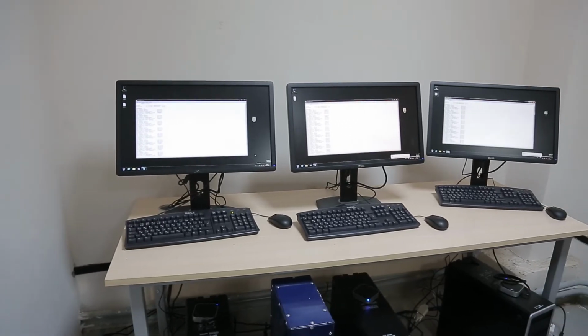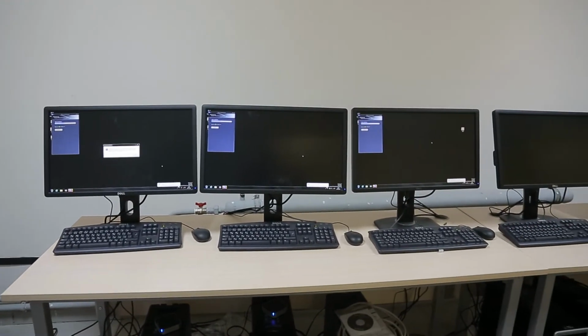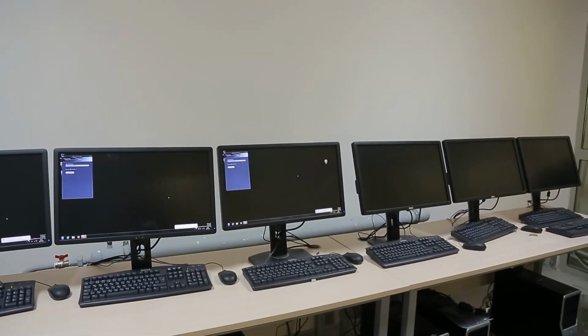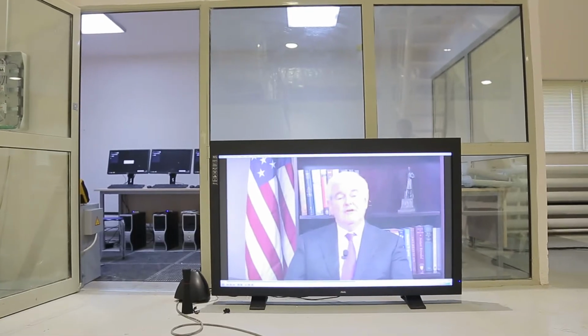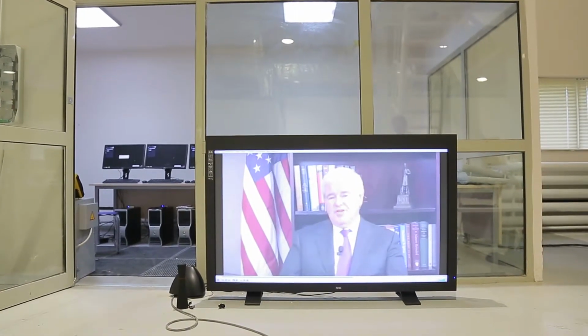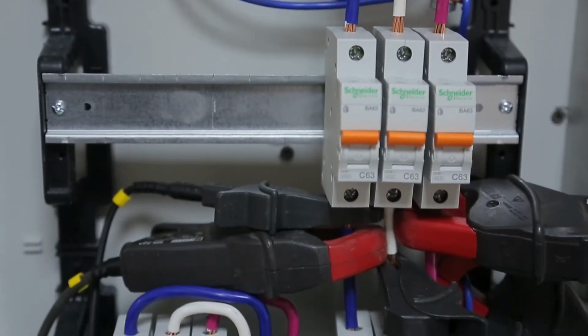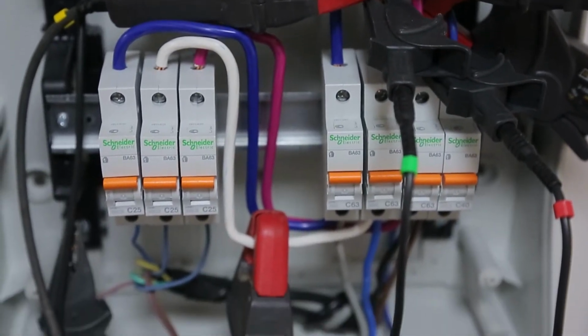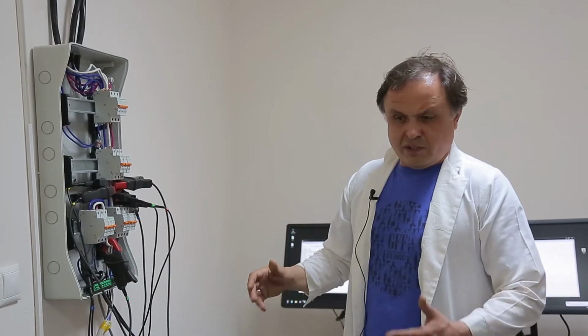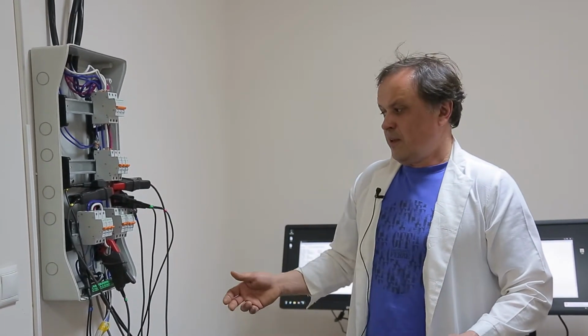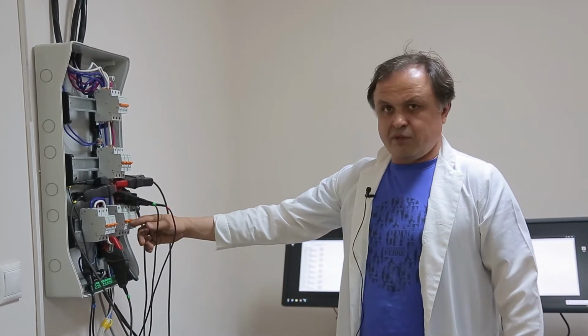The next know-how has been tested on the operation of a server in a small data center. Accidental situations will be modeled in a three-phase network, specifically the breaking of neutral or any of the phases. Besides the servers, a plasma display with a diagonal of 150 cm is connected to the three-phase network. We know that in the case of breaking of neutral in a three-phase network, the phase voltage is increased from 220 to 380 and sensitive equipment breaks down.